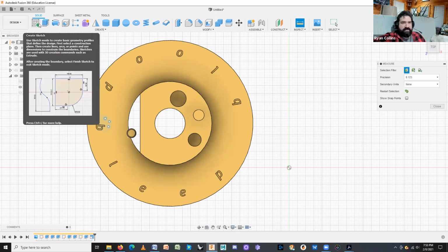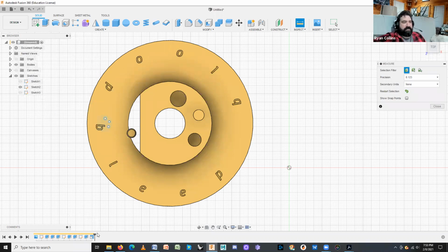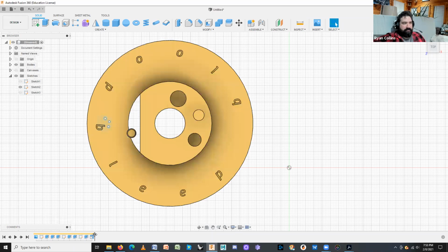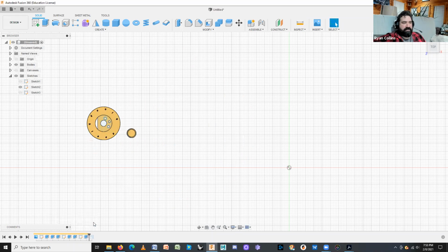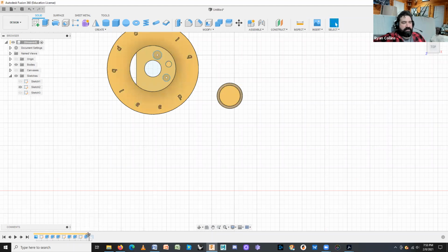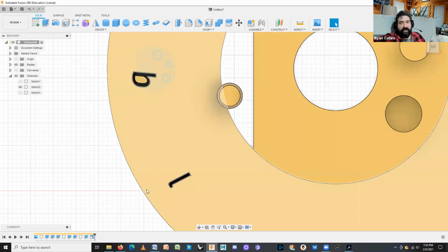Play around with the extrusions, but remember that everything is reversible, or at very least, I'll show you in the history slider. I click and drag, and I can go back in the history and start over or chop stuff out, whatever. Say, oh, poop, I should have made some adjustments before I scaled the whole thing up. Move the history slider before the scale. Now, anything you do will happen before the scale. And then when you finish, bring it back to current history, and it'll be giant again. It'll recalculate. Bunch of oddball stuff, but play around.